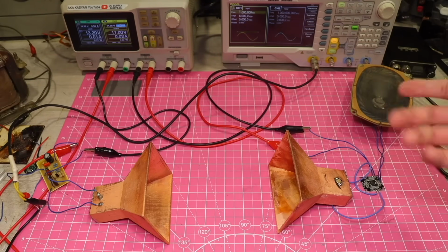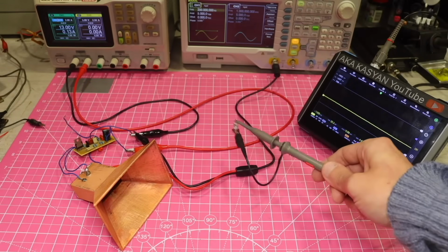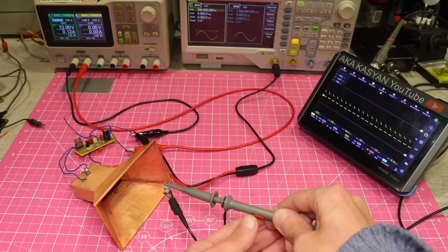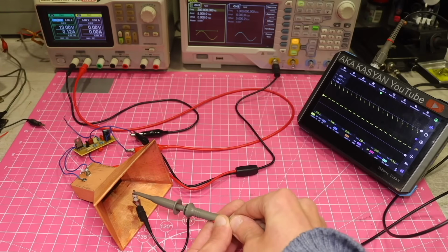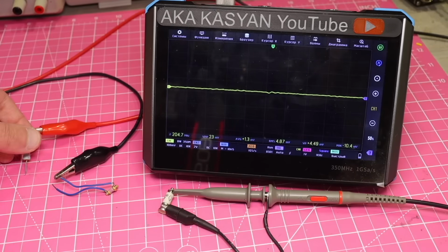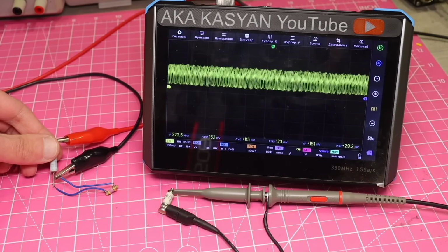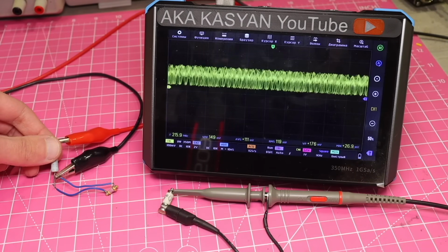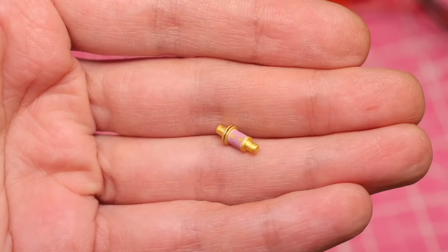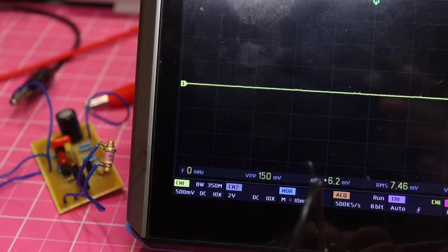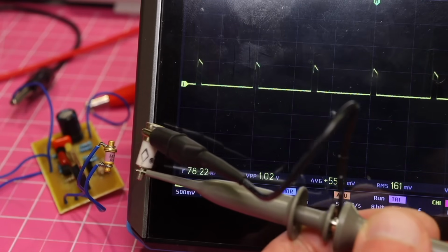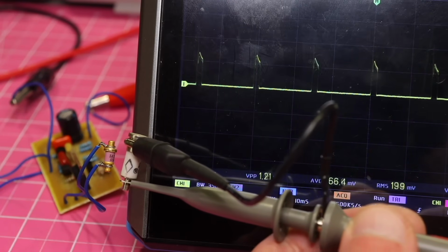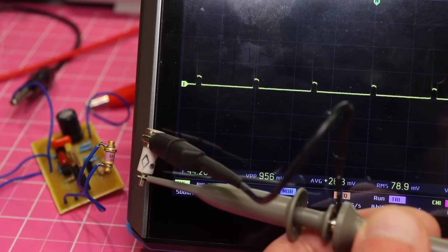A certain condition is required for the Gunn diode to operate. It needs to be supplied with a certain operating voltage, which is also called the bias voltage, usually from 5 to 10 volts. The value depends on the length of the semiconductor crystal. At the same time, Gunn domains are formed inside the diode. Negative differential resistance appears, and the diode becomes an active microwave element.